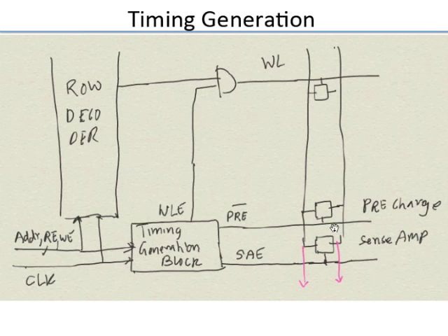In addition, this is the array of memory cells, and these are the vertical bit lines. What I've shown here is the pre-charge circuitry. If you recall, the pre-charge circuitry was essentially two PMOSs pulling each bit line to VDD and then one PMOS shorting the two bit lines. So there are three PMOSs.